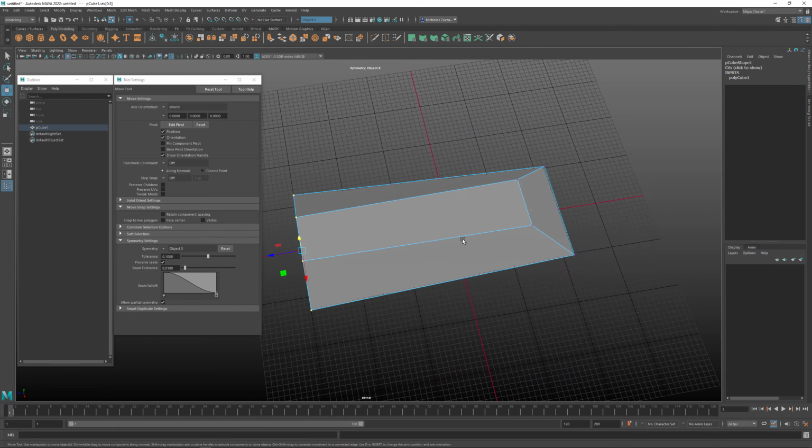I'm going to hit Control D again, hold down X, and you can see how we can keep building off of this and extending out. We've got these different objects at that point, and then we can move these. I do think this is kind of a cool feature: if you hold down Shift now while you drag out, it drags out a copy. So you can drag out copies that way. And if I hold down Shift and drag out, and if I hold down X while I do that, I can drag out a copy, and it will be snapping to the grid for us.